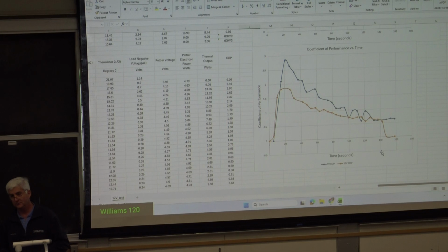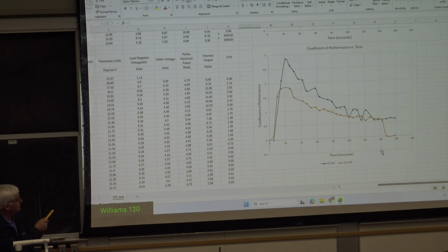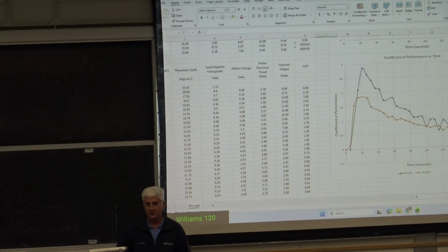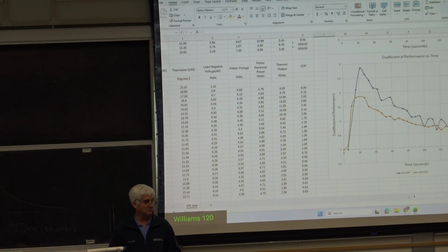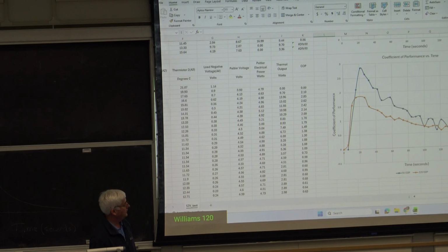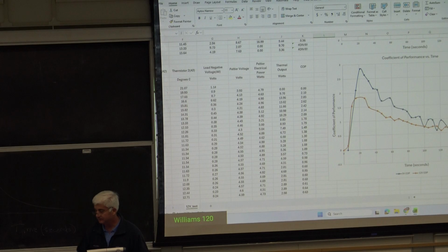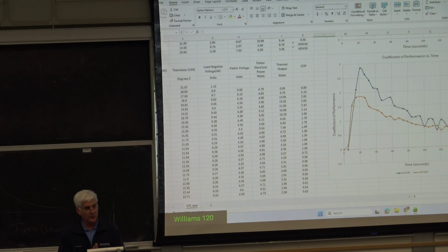And that's what I saw for cold climate heat pumps when I was an engineering manager actually doing the testing. We would see COPs of like 3, 4 using refrigerant R-410A. And yeah, that's why heat pumps are a good deal. You put in 1 unit of energy, you get 3 units of energy out. So pretty snazzy. Any questions on the lab, folks? I thought it was relatively straightforward, but I did catch a bunch of people. Okay. Moving right along then.